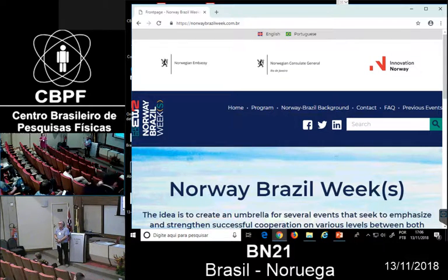At the same time, the North Sea is suffering on CO2 EOR, because if you do the EOR, you need a lot of CO2, not just a little CO2 from here and there. You need millions of tons of CO2, and it has to come steadily in a short period. At the same time, it's not going forever. If you have CO2 capture from a power plant, it comes for maybe 50 years, but for CO2 EOR you only need maybe 5 years for a particular field. So it's a mismatch between supply and usage.